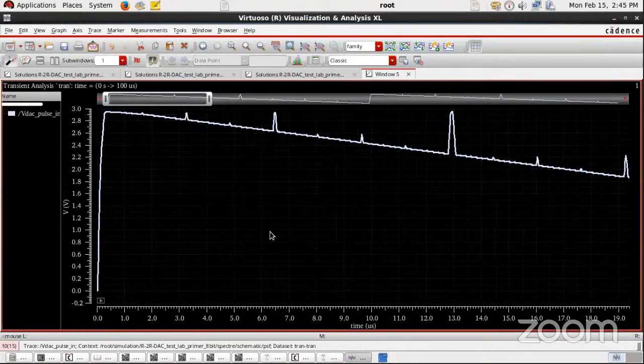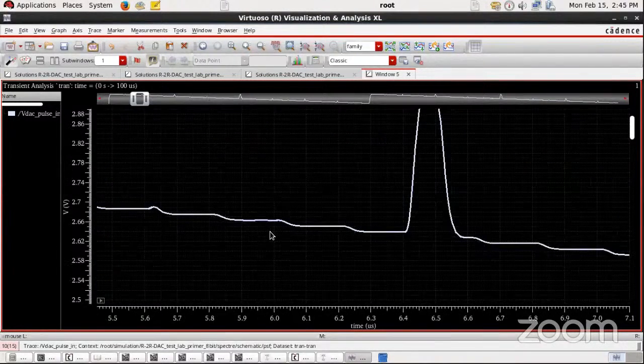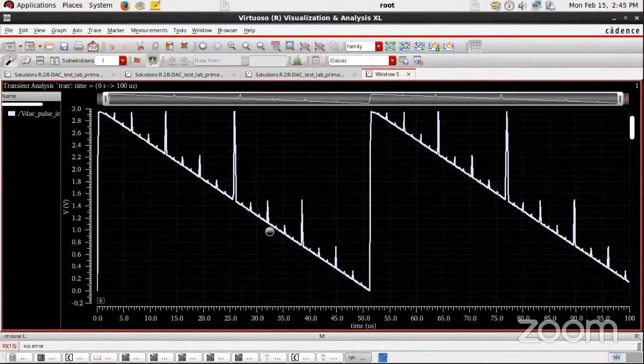It will not be a definite step, because here we have made use of MOSFETs, resistors, etc. So we cannot expect a definite step. But in order to get it, you can make use of filters. You can use an RC tank circuit, a low pass filter, or a high pass filter, and the compensation circuit can be made even stronger in order to reduce these spikes and all.